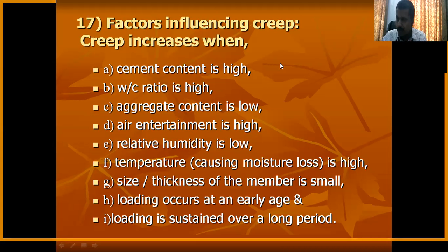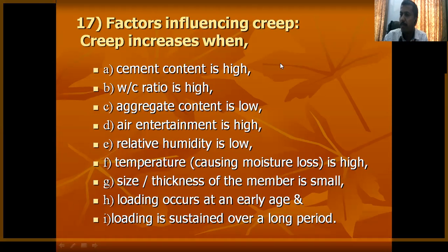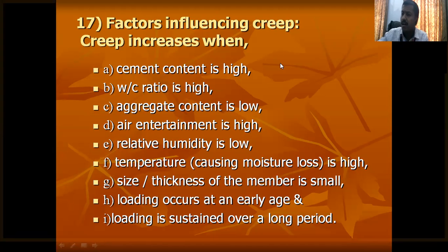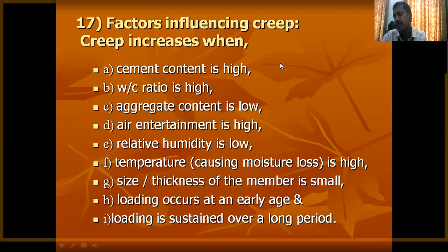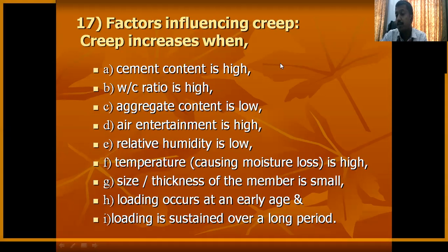Yes sir. Okay, so the first concrete block has a strength of 10 MPa, the second maybe 9 MPa, the third 11 Newton per mm square, maybe the fourth one 12 Newton per mm square. So the difference between these strengths is not going to vary by more than 5%. We take the average of these 4 values and that is the characteristic strength.